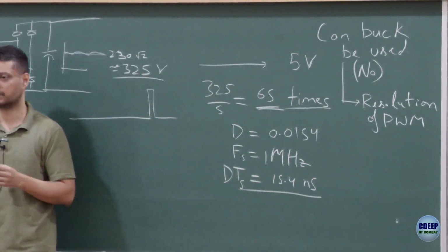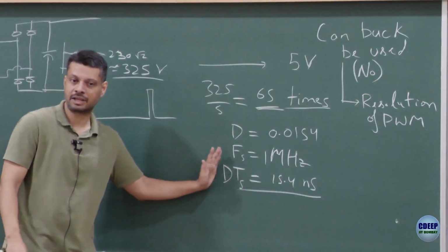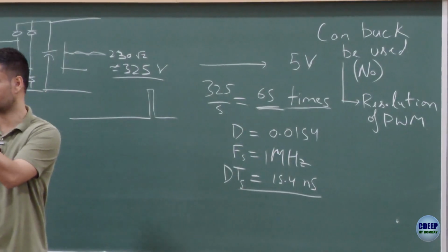That is going to be one practical challenge. Theoretically you can do it, but practically you would have to use a very high-end processor, or you can shift to analog control, which is also a possibility. But if you are trying to do it with a digital microcontroller, it's going to be a challenge to generate a pulse precisely of a very, very short duration.